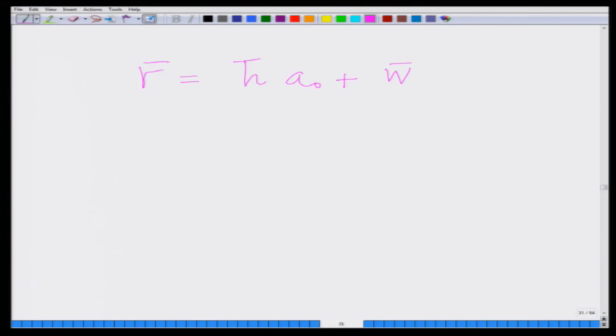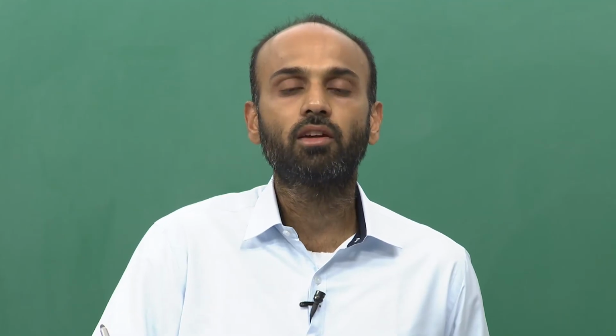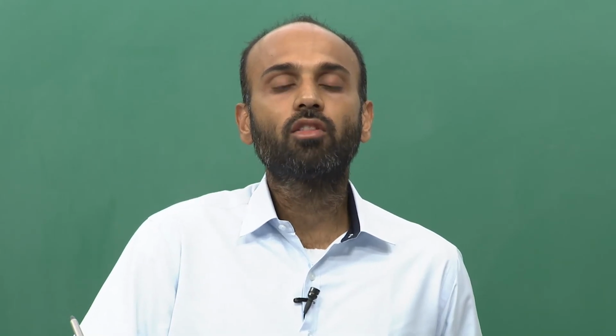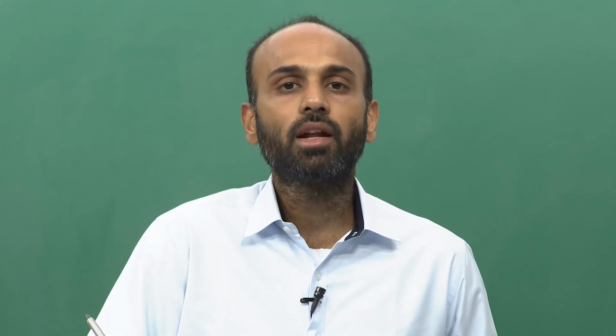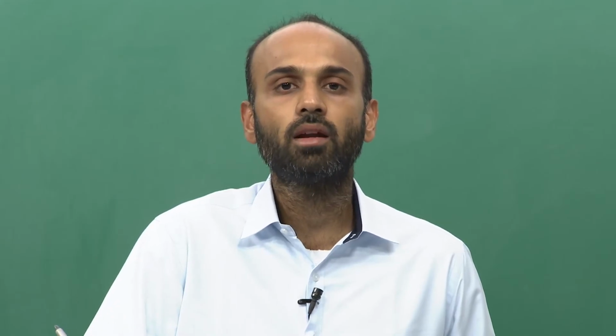And if you look at this model, it is in fact exactly identical to the model of the multiple antenna wireless communication system, where the different channel coefficients across the antennas are H0, H1 up to H L minus 1. We had an exactly similar model, that is R bar or Y bar equals H bar x plus W bar.